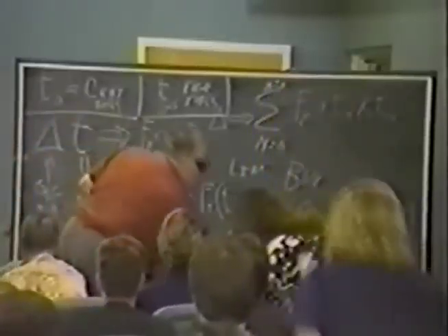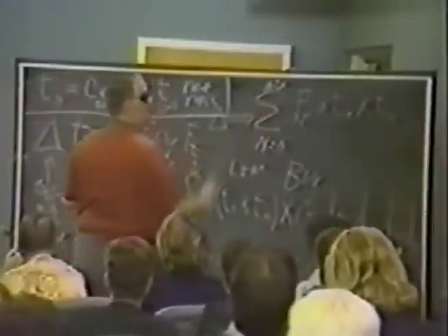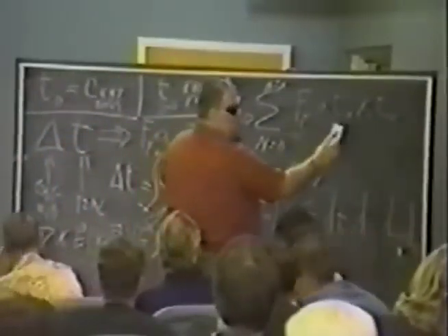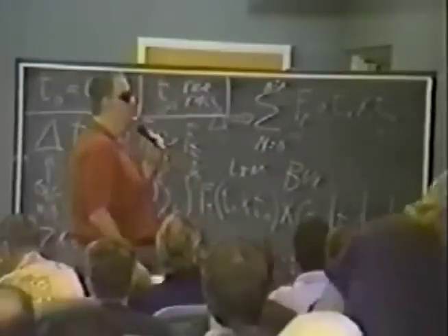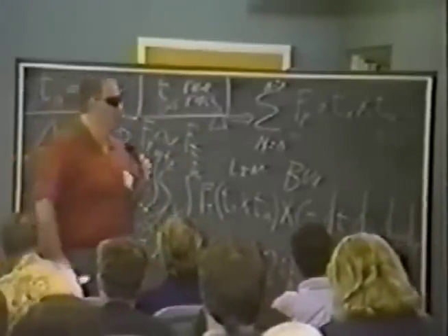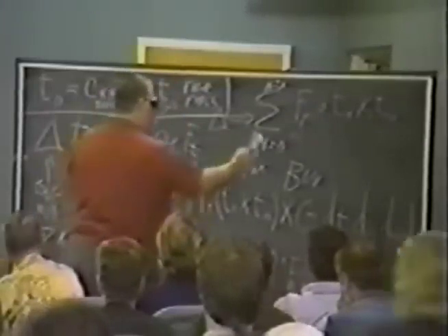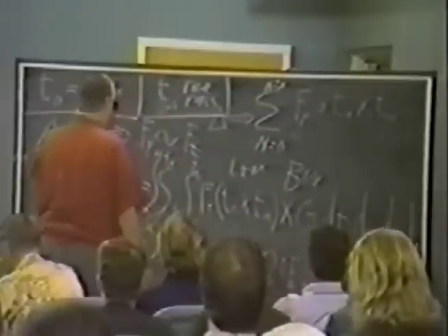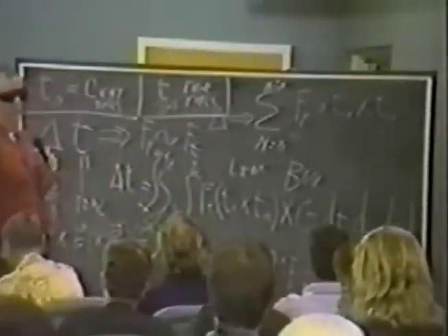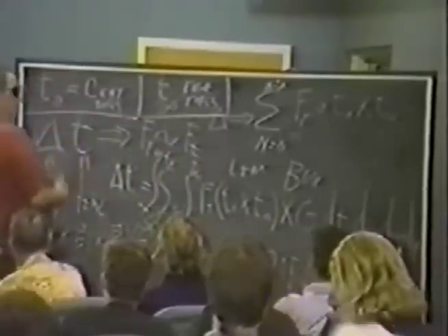Tell us again what n equals 0 again. Here? This is the initial summation of your frequency times 0 times infinity, where you're going from the 0 harmonic to the infinite harmonic. This is everything. This is the whole universe. But of course, we're limiting the bandwidth. So now we're breaking it up into integrals, where we go from a minus f to a plus f, which is giving us the bandwidth factor, because our systems are not infinite bandwidth. At least not yet.